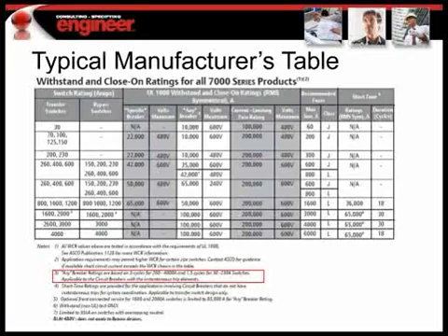And for switches greater than 60 amps and larger, the UL 1008 test involves testing the withstand rating at 3 cycles. Another important point to note is that some of the withstand ratings published by transfer switch manufacturers are not in fact withstand ratings as defined by UL 1008.